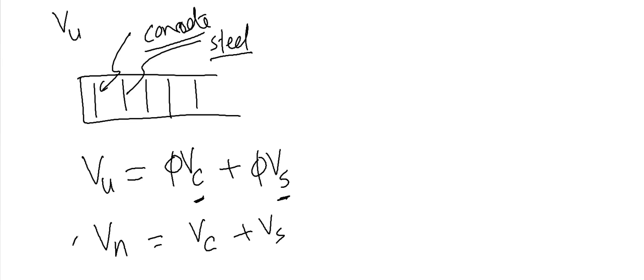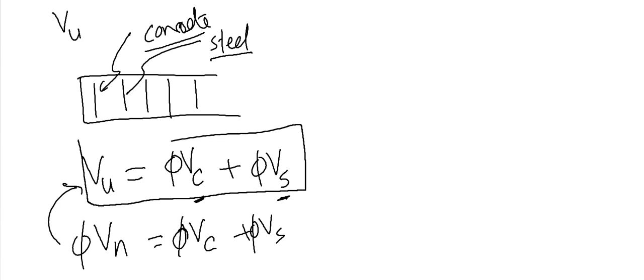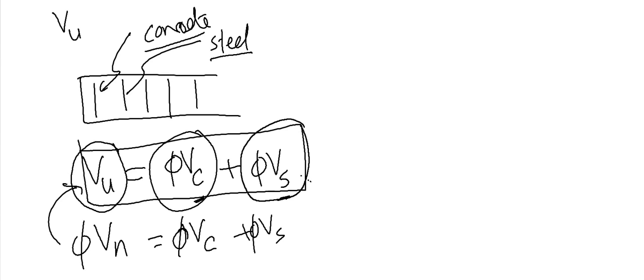Now, if I multiply phi here, it will be this equation. So this equation we use in our design. At least from this equation, you learn that whatever your design shear force, concrete will take some, your reinforcement will take the rest. Now, how much can plain concrete take?